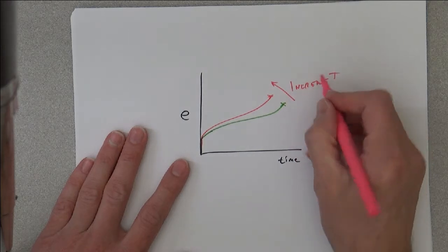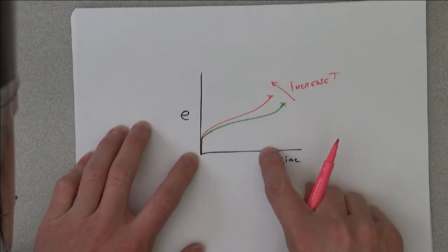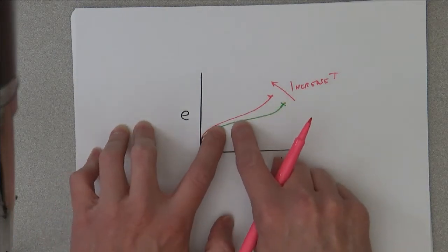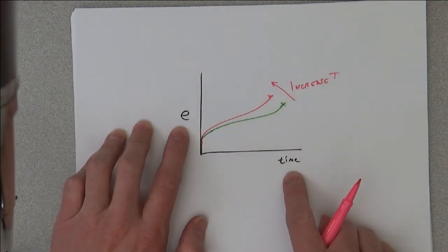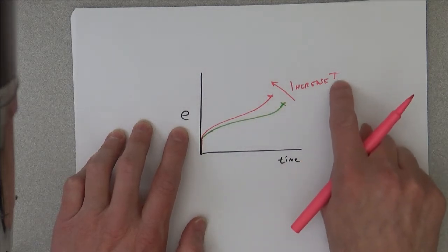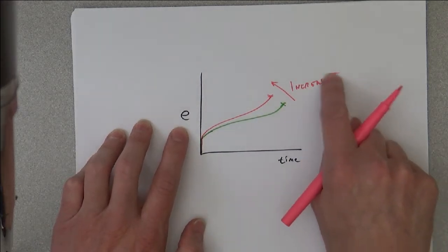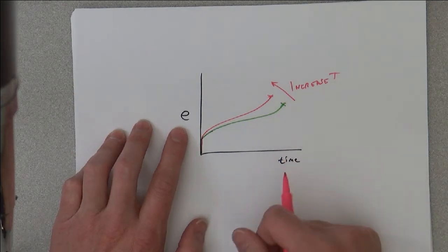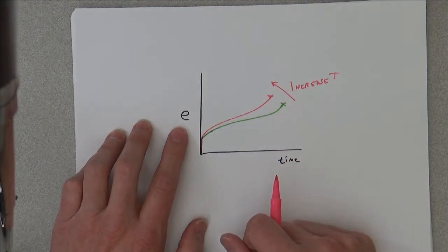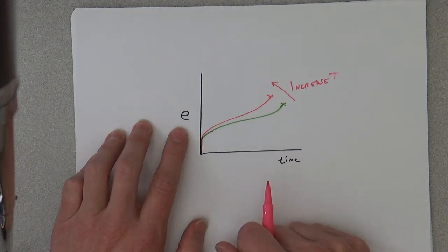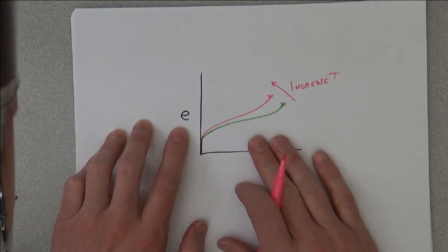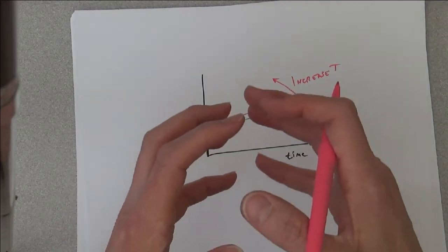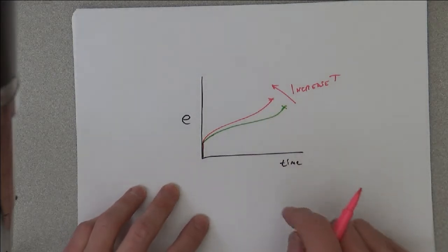As you increase the temperature, then the strain rate increases, the strain rate being the slope of the strain versus time curve. And that's because typically the processes involved are thermally activated. So we have that Arrhenius relationship that tells us about the activation for vacancies to hop or for there to be a small shift in a grain's positions.